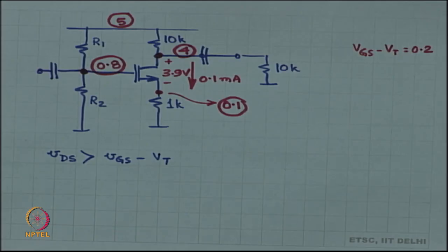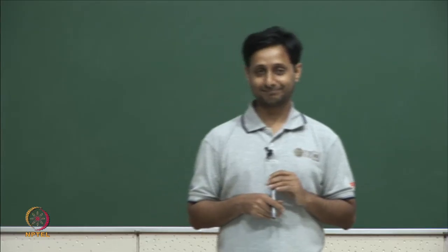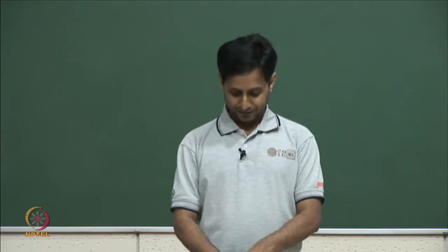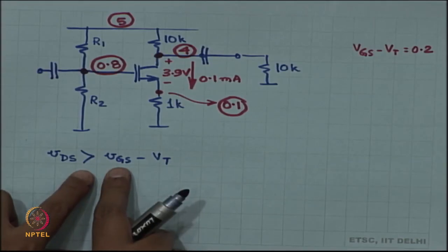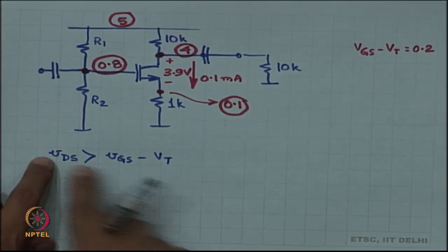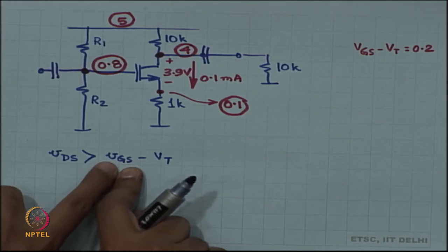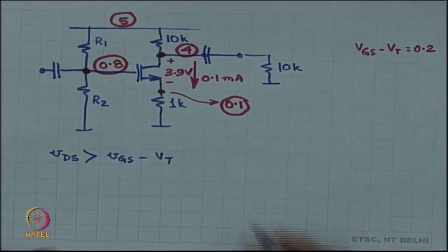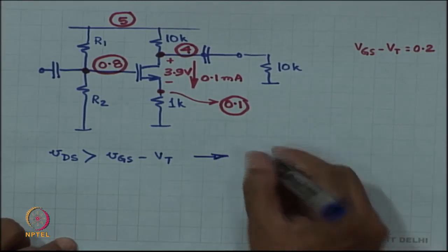Okay. So, earlier we had the source as a static voltage, now the source is no longer static, all right. But the cool thing over here is that the source voltage is going to cancel out. VDS is equal to VD minus VS, VGS is VG minus VS. So, the source voltage really does not matter, cancels out.